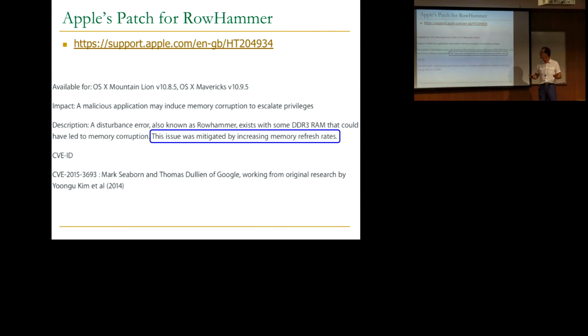I think those are very intrusive. This is also intrusive in a different way, but this is very easy to employ, right? If your memory controller has this configurability, and most memory controllers have the configurability to change the memory refresh rates, you can reduce the vulnerability. They didn't tell by how much. They're probably limited by, maybe this doesn't get rid of all of the errors also, right? We don't know. Is this the thing that drains the batteries on the iPhone? No, maybe they have a different plan for that. I don't know. It might be. But this is actually not good. As you mentioned, this is not a good solution because it's across the board. We want to get rid of refresh as opposed to increasing refresh.